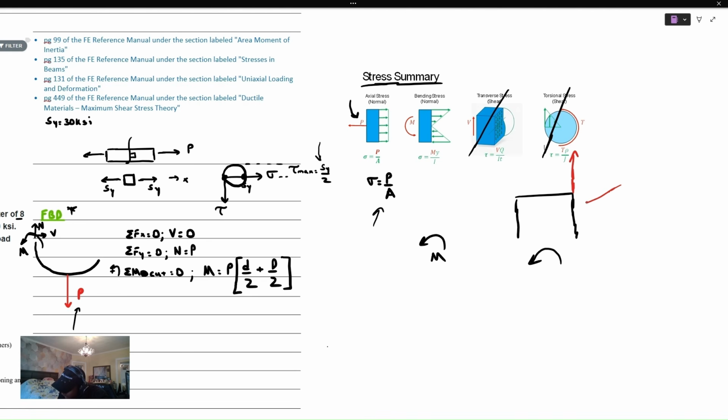This is the inside of the hook, and this would be the outside. So you can see that if we drew those forces, it's clear that we would have the most tension on the inner surface of that hook. I'm going to draw this like this so that we understand. We connect these two in a linear fashion, and what we're going to get is the most tension on that inner surface.